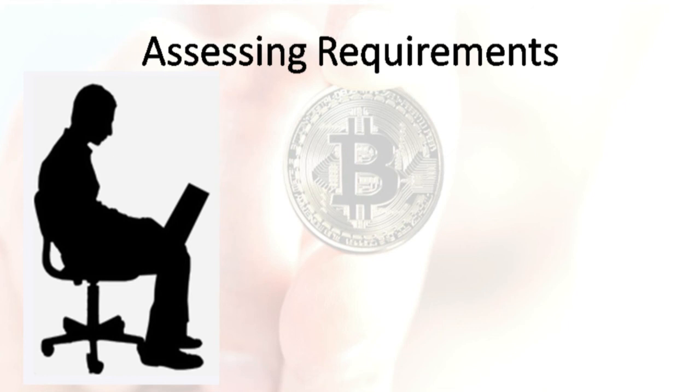Now, it is not too difficult to get current power consumption, but projecting what you need for the future will be the harder part. With this, you will need to provide an estimate of, over a reasonable time period, how many extra mining rigs you can imagine being deployed, and how much power each of these mining rigs can consume. The tricky thing is that mining rigs actually have different power consumptions, so it's a bit harder to gauge. But you can just ballpark it based on what you have in your current model of mining rigs.